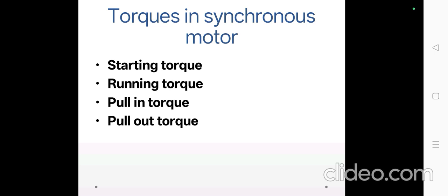When the motor is overexcited or underexcited, the power factor changes are more significant than the changes in the current and load angle as load changes. When the motor is overexcited or underexcited, the power factor tends to approach unity as the load increases. Next one is the variable operations of the synchronous motor, that means variable excitations.